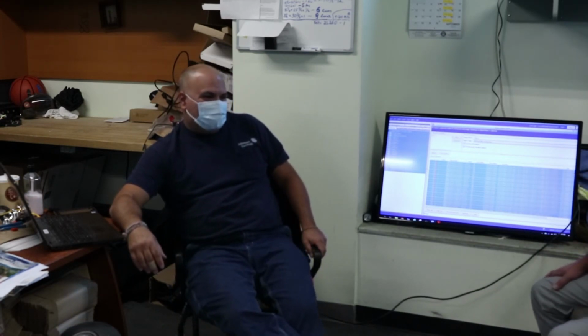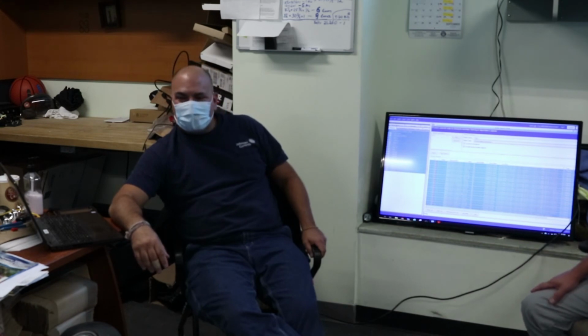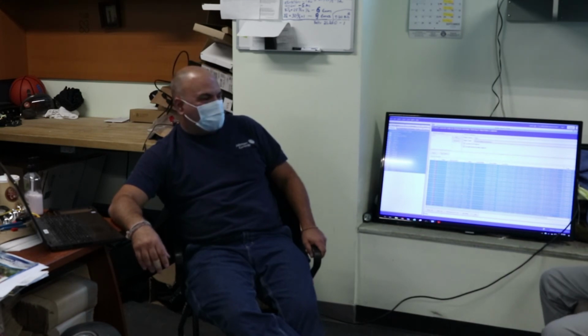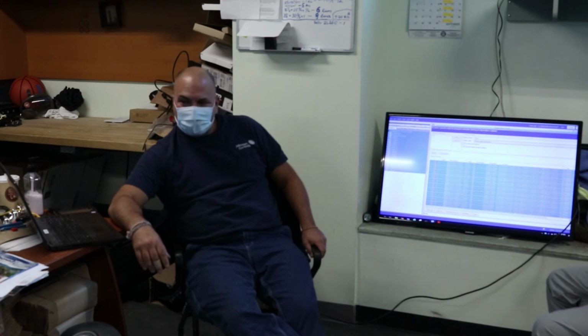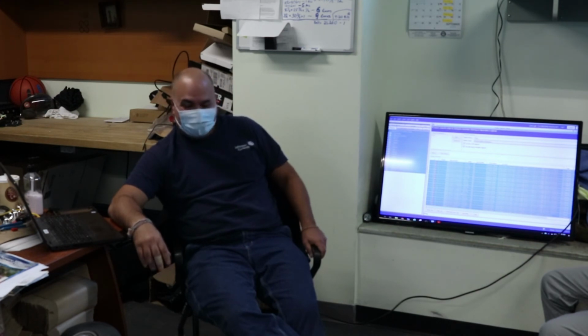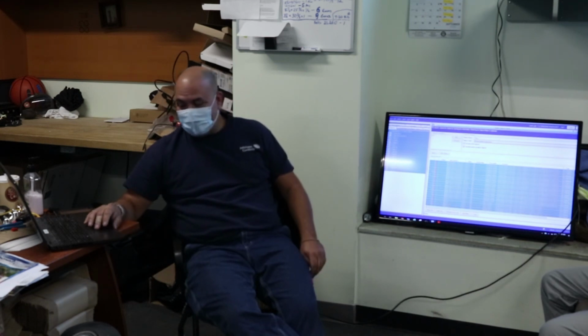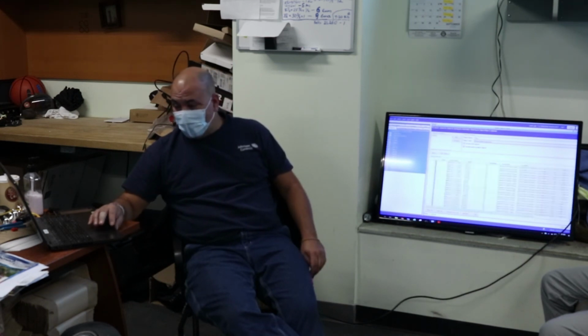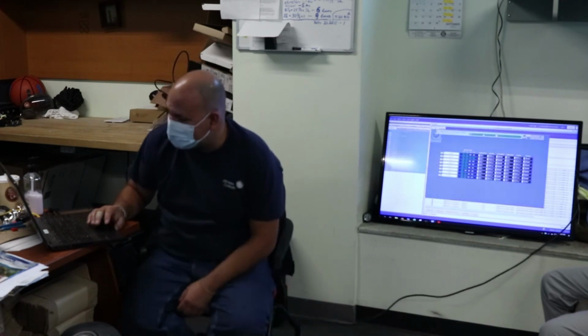Curiosity killed the cat? What's the max discharge air you can get out of the VAV? What do you run your secondary hot water to? 160 or 170. That hot, huh? I think it's on a reset schedule based on outdoor air temp. Well, you should be able to tell me that. I don't know offhand, and we could look. Should be.